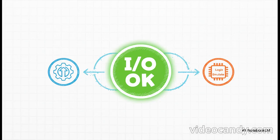And success! Once the program downloads and you switch the controller into run mode, you should see this fantastic little green indicator light up. I/O OK. This is exactly what we wanted to see. It means Studio 5000 is talking to the I/O module through the CPU, all virtually. Our entire system is officially online.